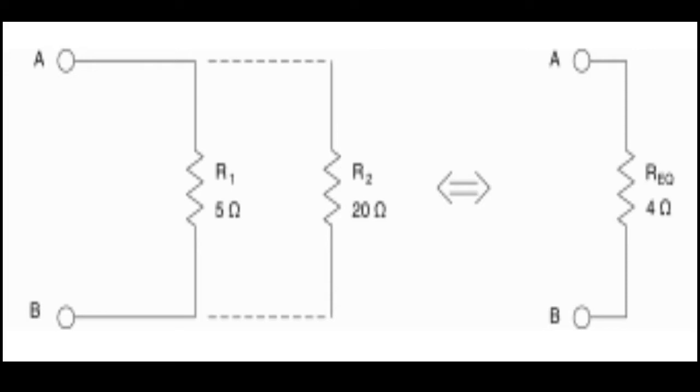Electric current, like water, will flow through any path provided for it. When the resistor is connected across a power source, current will flow in the resistor. When a second resistor is connected in parallel with the first, additional current will flow, meaning that the effective resistance of the circuit has been reduced.